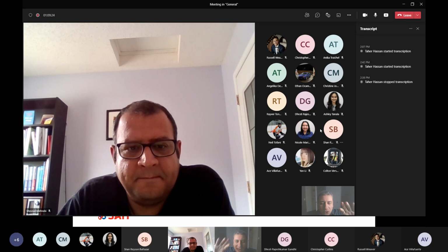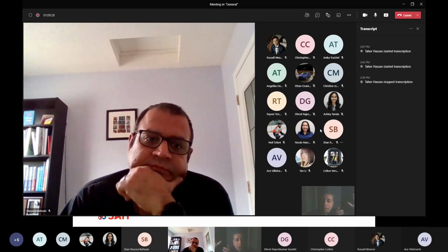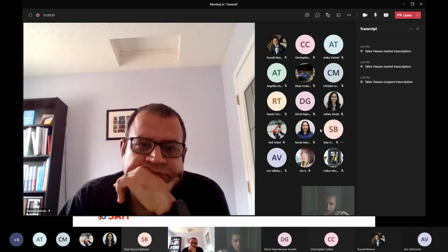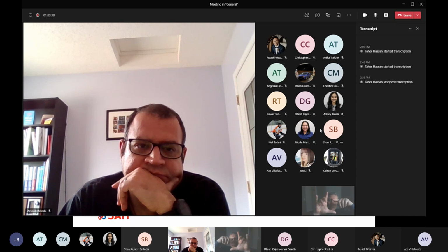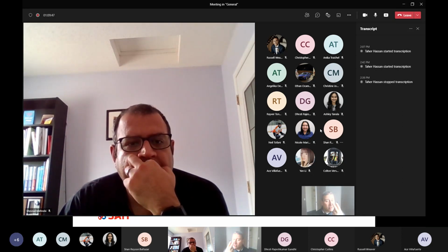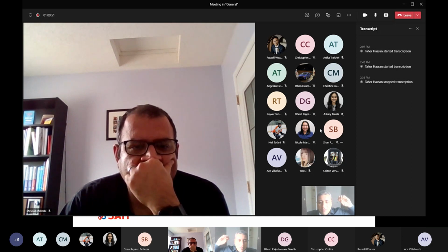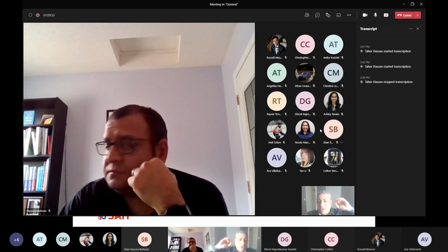So by the way, I know it's not in the video, but at the same time we have a computer, so all the data is simply logged into the computer, and dynamically on the computer you should see the graph between the stress and strain. Remember, and I'll show you the graph shortly, we're trying to establish a relationship between two variables, which is stress and strain. So the graph will develop ahead of you, and you will see visually when the specimen is close to failure. Even the machine will tell you, remove it now, remove it now.